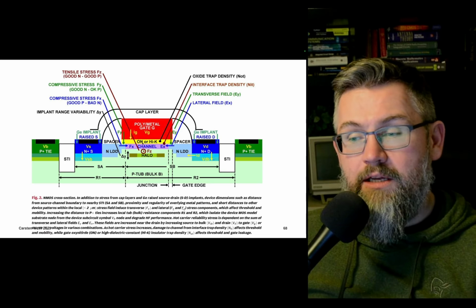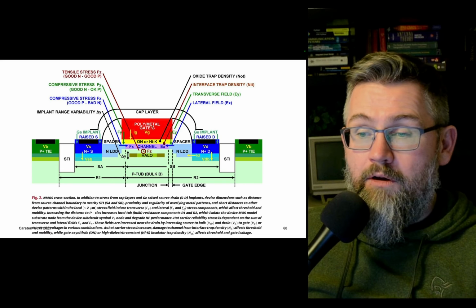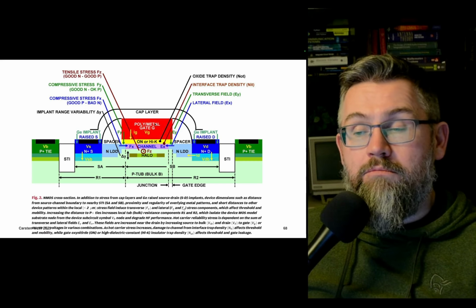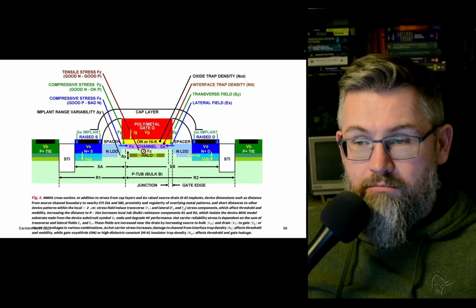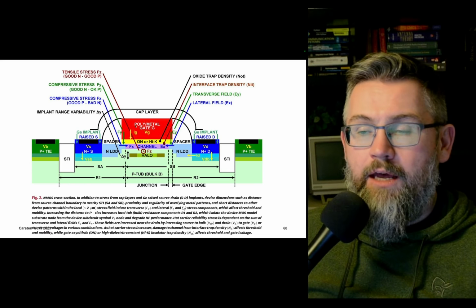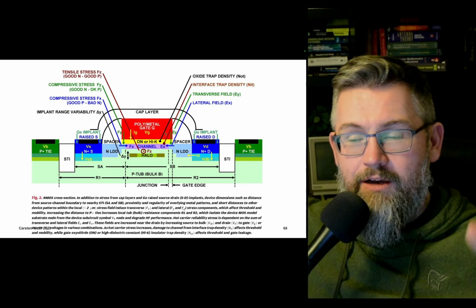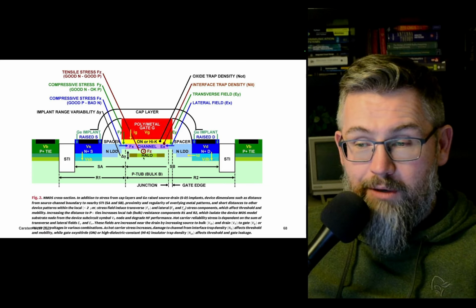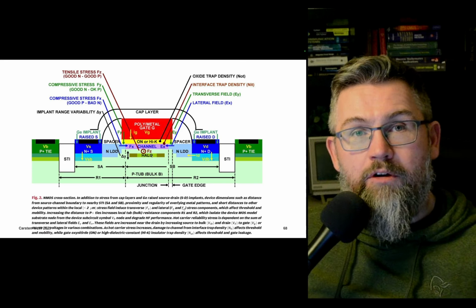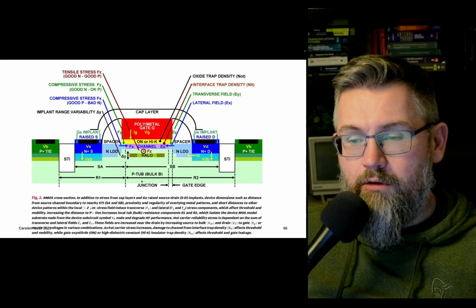These days it's usually maybe even hafnium oxide, or a high K oxide and a metal gate. And yeah, so this gate material might be polysilicon, it might be metal, and then across the transistor maybe you have a cap layer to strain, to pull the silicon. There might be halo implants to reduce the amount of electrons that can be injected at high drain source voltages.